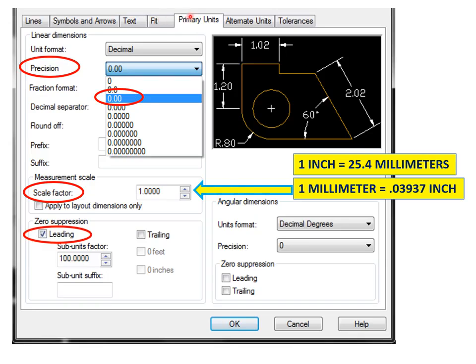But if your boss tells you, hey, I need you to change your dimensions from inches to millimeters, so instead of 2.02 inches, your boss wants you to change this to millimeters, about 51 millimeters, then you have to go to scale factor. You go to scale factor, and you would change the 1 to 25.4.